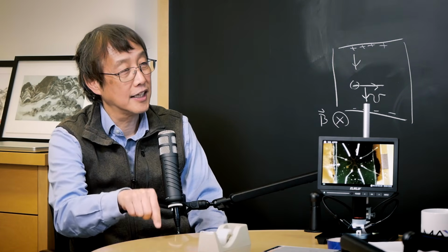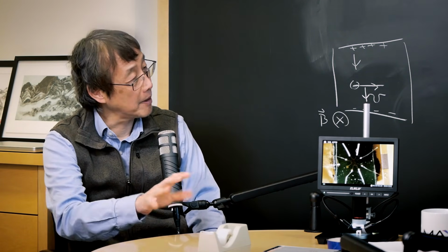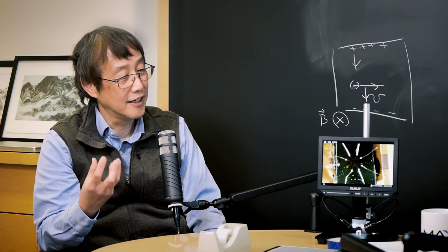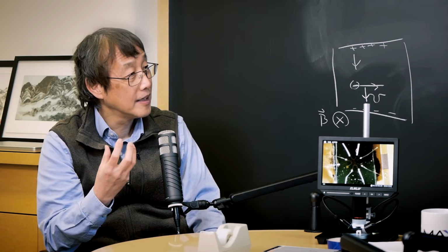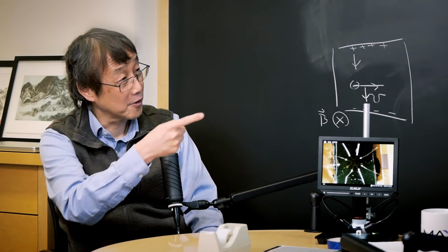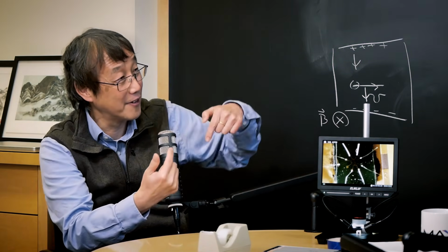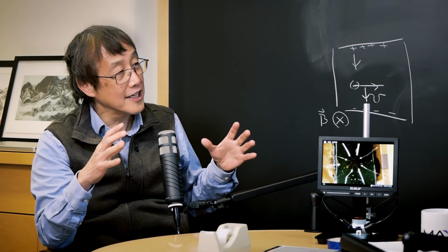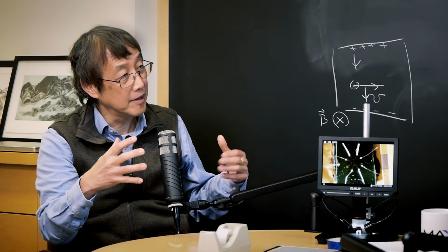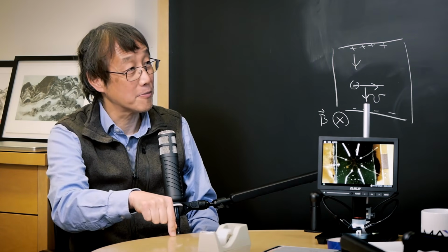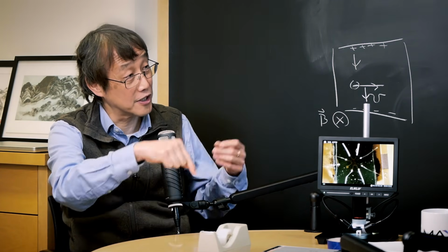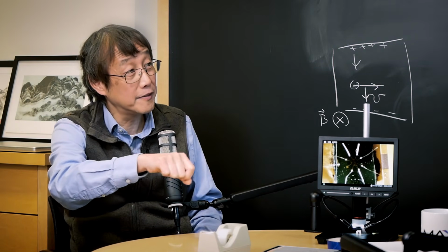So I decided, all right, maybe between Haas's and Rodney's methods, there may be a way that we can think about. The way that I thought of is maybe using the AFM, but instead of an AFM tip, going back to the nanotube on top of the AFM, right? Instead of doing that, what if I make the graphite block the AFM tip and then bring the AFM tip down onto the substrate, where I can control the normal force, which will control the friction, and try to cleave it off in a more controllable way.